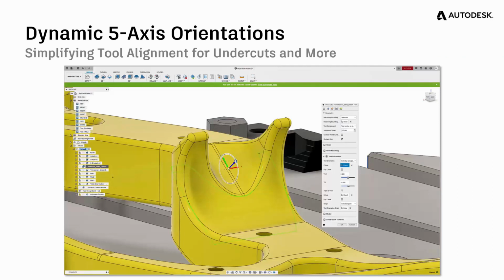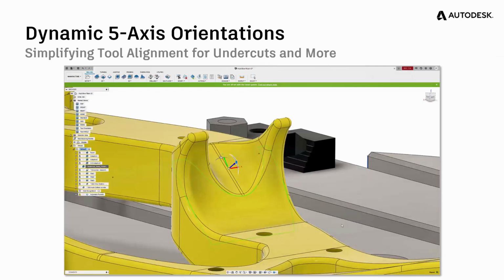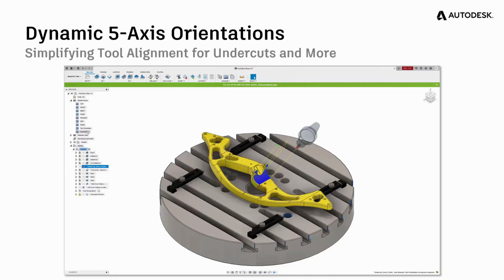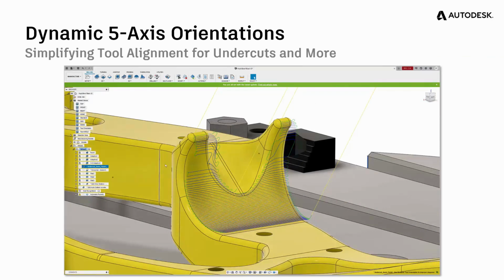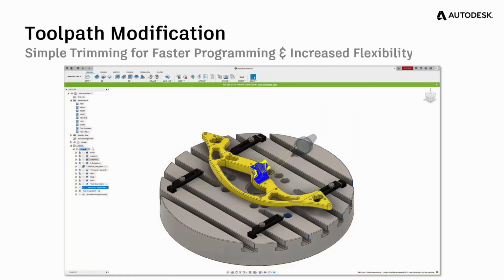And then dynamic drag handles can be used to drag the cutting tool into a different rotated position, allowing you to optimize the rotation of the machine tool to machine undercuts more easily, explore using shorter, more rigid cutting tool assemblies, just basically improve the way you machine with your 5-axis machine capabilities. So this is great for 3+1, great for 3+2 machining, as well as 5-axis machining more broadly.